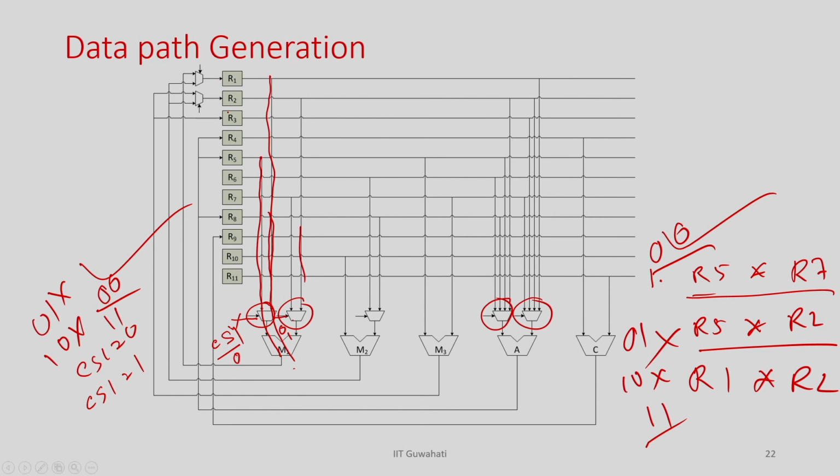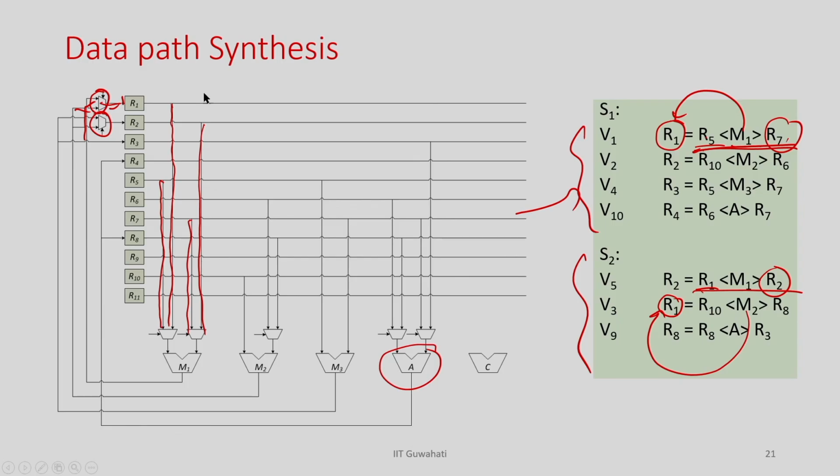It may be that in every clock I am not writing this register, right. So, if I give enable equal to 1, then only whatever data is coming here will update the register. If the enable equal to 0, it will ignore the data. So, for example, if you see here, R1 is getting executed here and here. So, R1, R2, R3 and R4, right. Other registers are not getting executed.